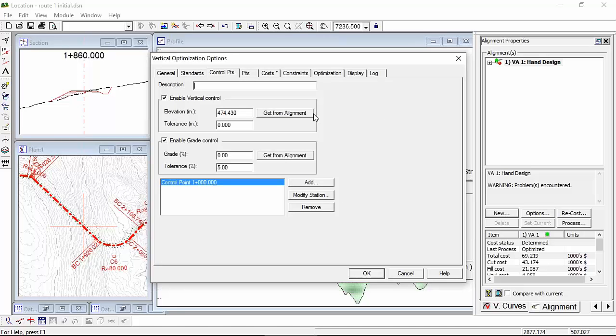Control points. In this case, I'm going to set the starting elevation with a minimum grade of 5%. Could be -5, doesn't matter. Starts at 0 ± or -5. That's a control point. You can use control points all over the alignment. Typically, they would be bridge abutments, culvert cover, intersecting roads, overland fill depth.